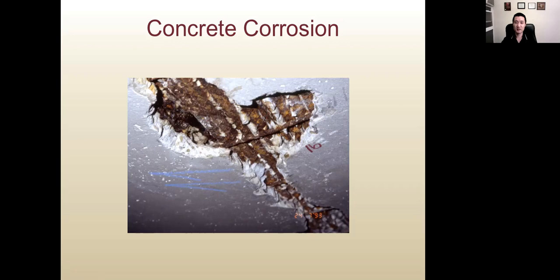Morning. Today we discuss lecture number 14, which is durability 2. We discuss concrete corrosion, which is corrosion of the steel reinforcement in concrete. We discuss sulfate attack and also durability of concrete in general.